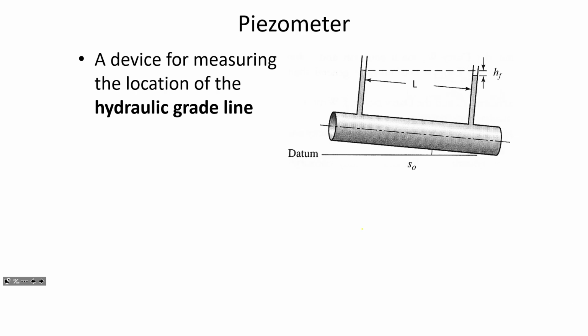One way for us to measure pressure changes is a piezometer. And you'll remember from fluid mechanics that a piezometer is just a simple way of measuring the pressure, because all it is effectively is a puncture in the pipe connected to a tube. And the water level will rise to a certain elevation to reflect how much pressure there is at that location. And so this pipe segment that's shown, if we had a certain length of pipe and the water level isn't rising as high in the piezometer on the right, then that would be an indicator of the flow direction. For one thing, we'd know that the water's flowing from the left towards the right. Otherwise, there wouldn't be that deflection.